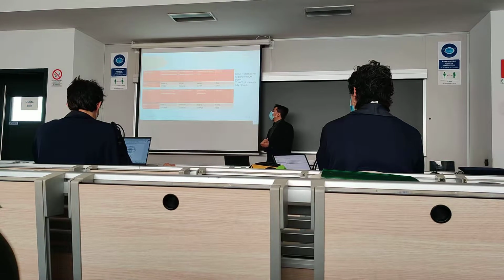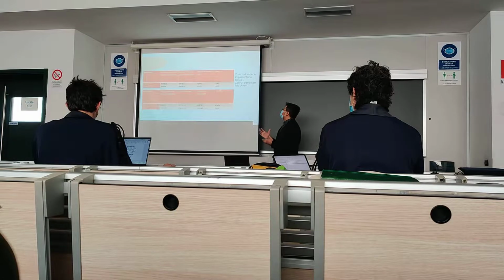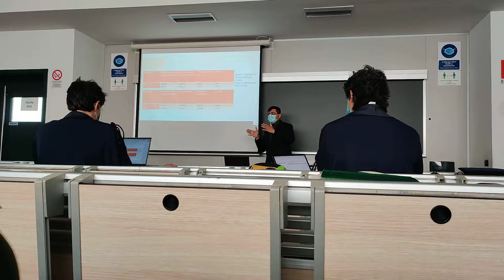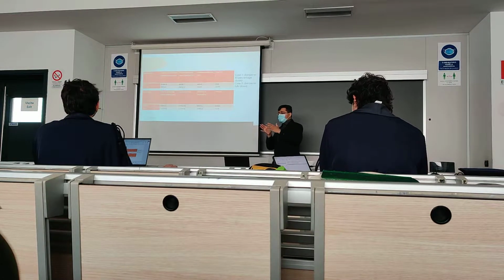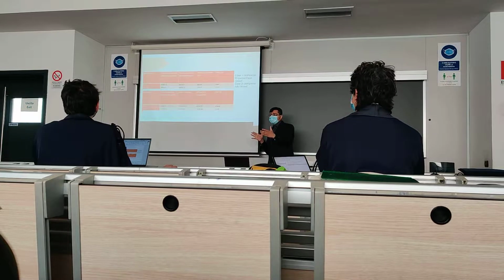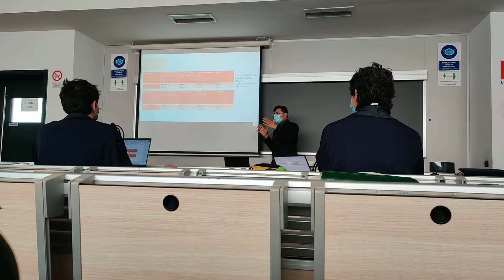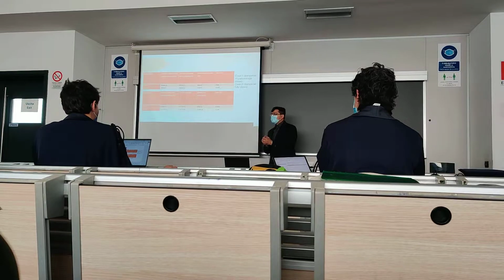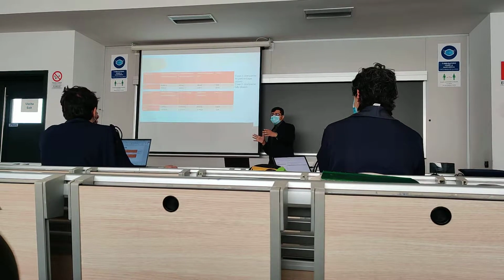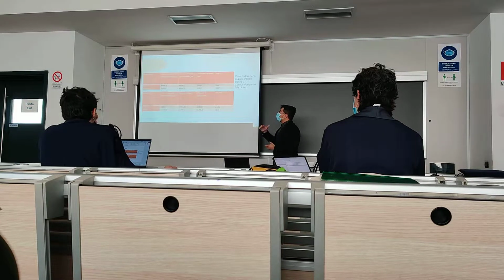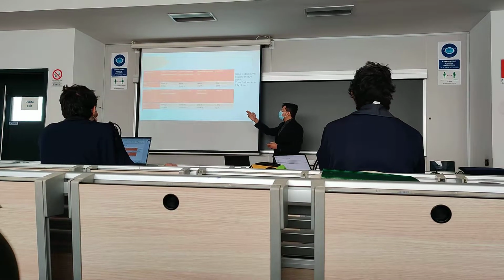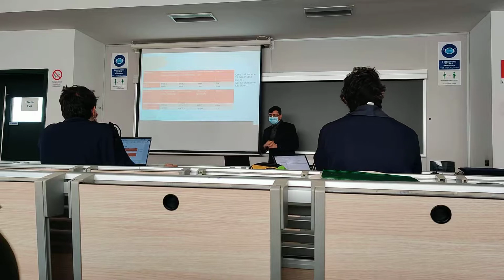In case one, the damper is the output of the external centrifugal test bench. If you close it, the centrifugal test bench will get pressurized. In case one, we closed it to 95%, and then we took the values for different RPMs, 2734 and 1791.